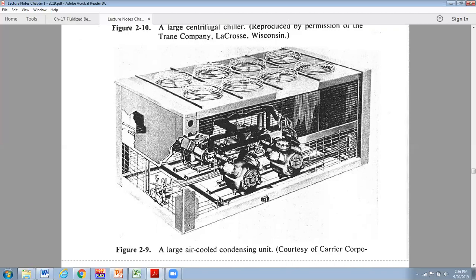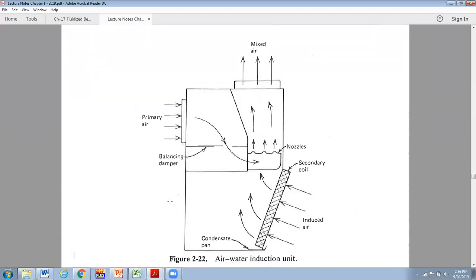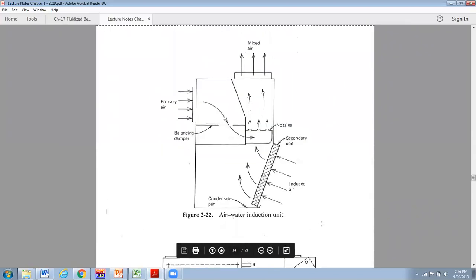These are reciprocating compressors. They show 4 in here, so they could be staged on one at a time. So you might have 25, 50, 75, or 100% capacity. So that's the way that can work. Let's see, moving on. Okay, we have some other types of equipment, just so you have some kind of an idea of what's out there in the world.